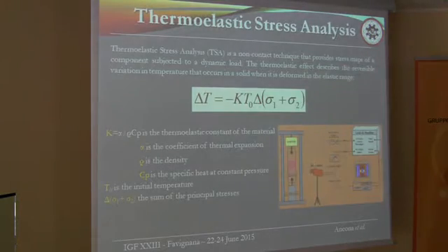So, in general, thermoelastic stress analysis is a non-contact technique that provides stress maps of a component subject to a dynamic load. So, in fatigue testing, we can relate the sum of the principal stresses to the temperature variation that occurs during the loading. This is possible through the thermoelastic constant K that depends only on the material.